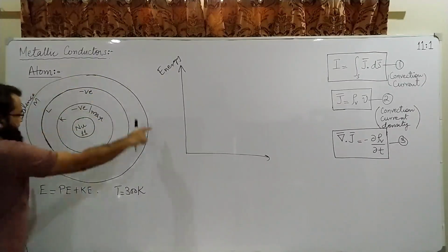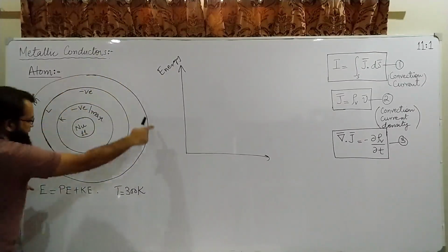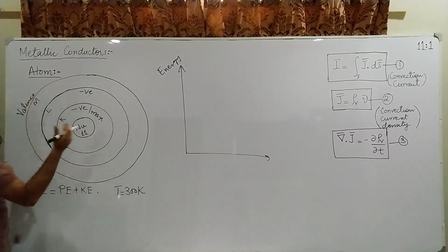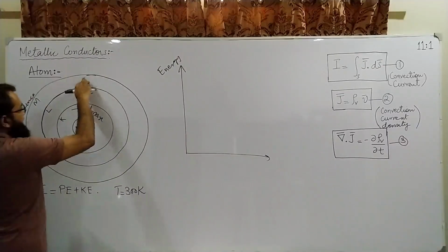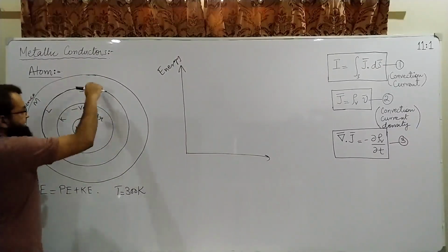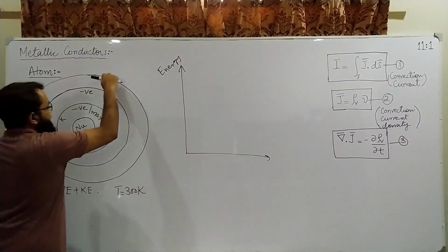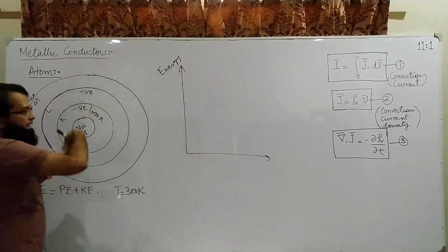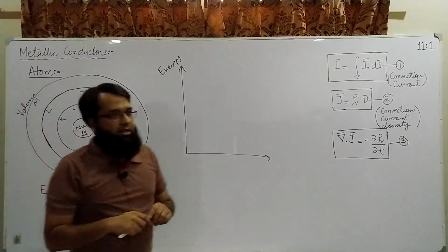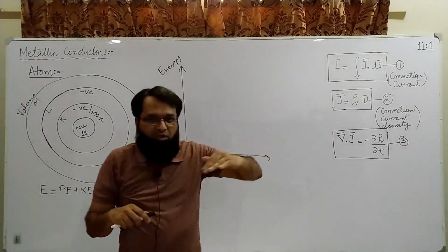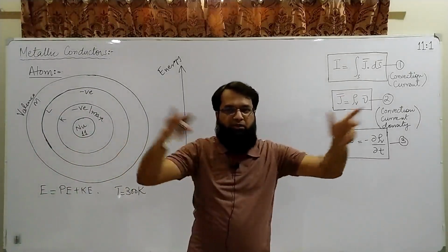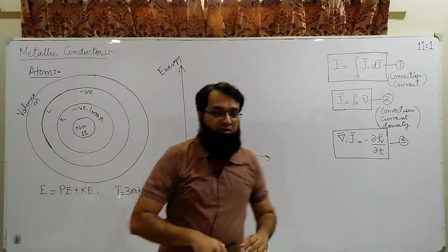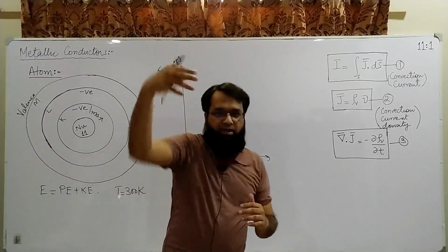This band has got the least energy associated with it. Slight absorption of energy by the atom or by the electron can set the electrons in the valence band to jump to the band in which, if the electron jumps, it will be free from the influence of the parent atom. That band is known as the conduction band.